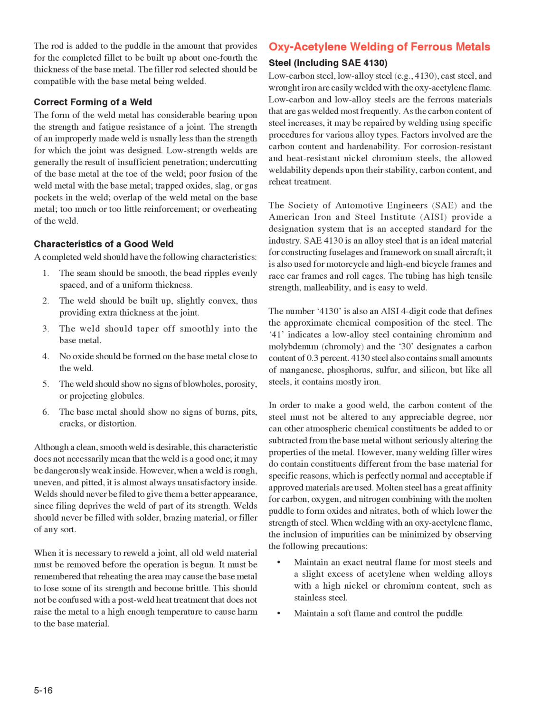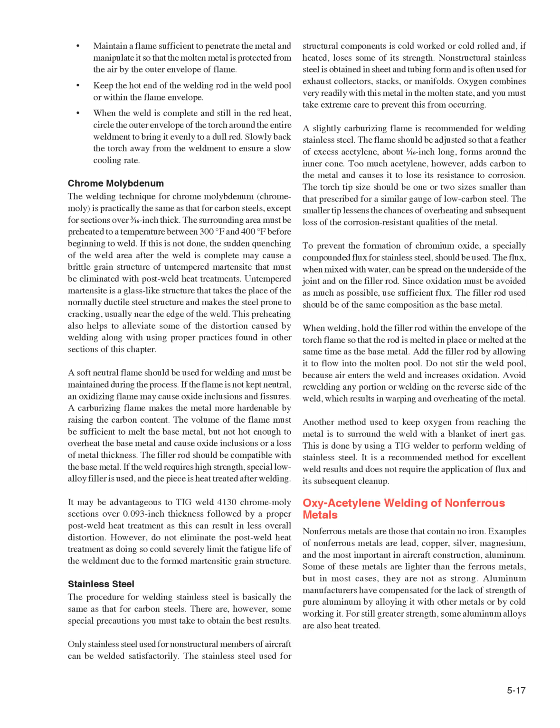Maintain a soft flame and control the puddle. Maintain a flame sufficient to penetrate the metal and manipulate it so that the molten metal is protected from the air by the outer envelope of flame. Keep the hot end of the welding rod in the weld pool or within the flame envelope.